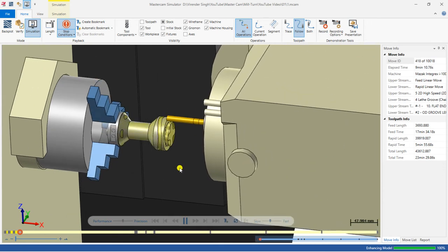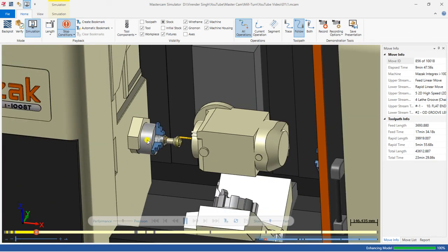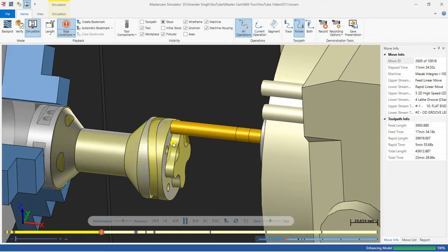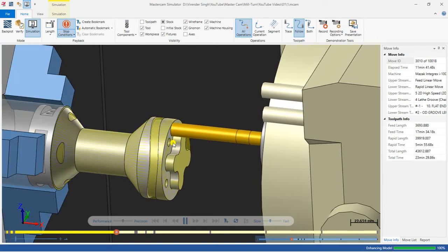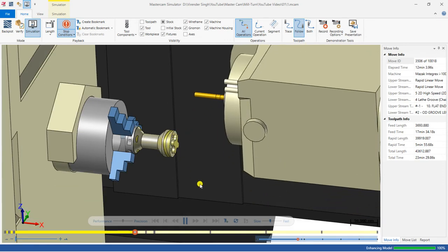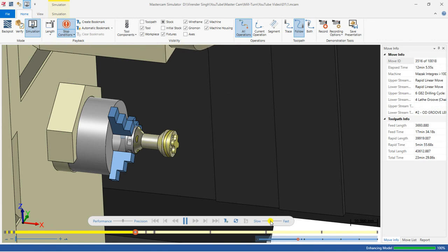So first is dynamic mill. Where I use this kind of milling toolpath, have a look. The C-axis is going to be tilting. The spindle comes to one particular specific angle, and once it's done, it starts cutting the outer. The C-axis is tilting in both positive and negative. Now it's successfully done. Once it's done, my next toolpath will come